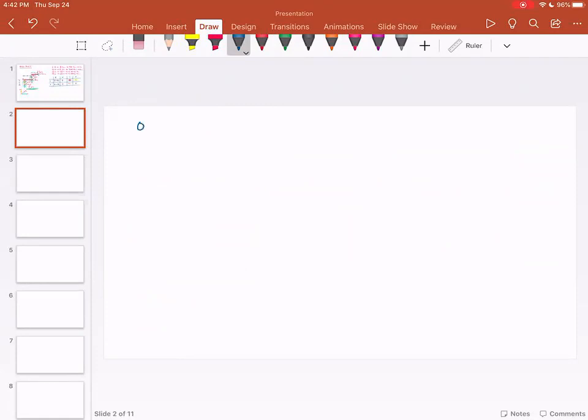If you want to find n minus 1 hn, this black box equation can be remembered by looking at the similarity of the form. The first term is cosine theta n, second term is sine theta n, third is 0, fourth is 0. This is the first column of your homogeneous transformation matrix.